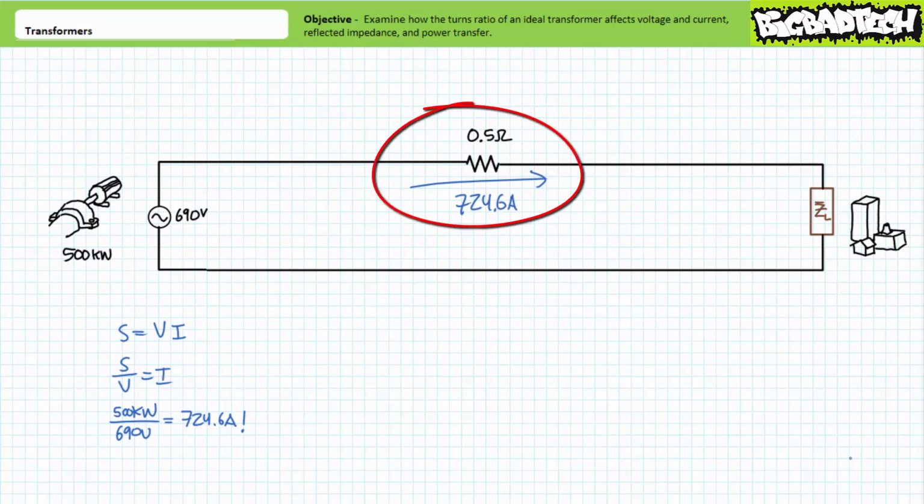Now, consider this generator being asked to supply power to a city 200 plus miles away with a long transmission line made of thick, highly conductive, extremely expensive material, modeled as a 0.5 ohm resistor. You'd think 0.5 ohms of resistance might not be a deal breaker, but recall that power is proportional to current squared times resistance. With such an astronomical amount of current being sent through this line, we might expect there to be a large power loss in the line alone.